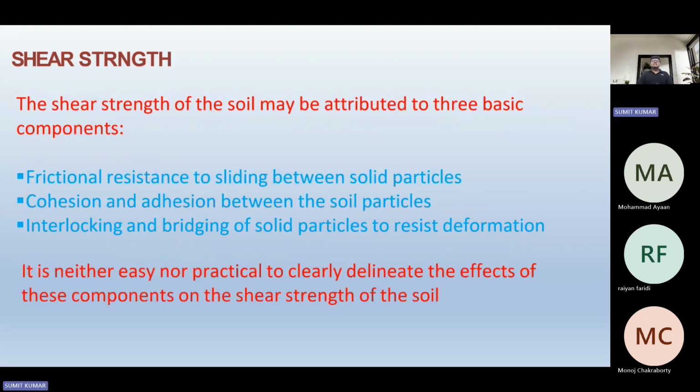Okay, so the shear strength of soil may be attributed to basic components like the frictional resistance to sliding between the soil particles, cohesion and adhesion between the soil particles, and interlocking and bridging of the soil particles to resist deformation.